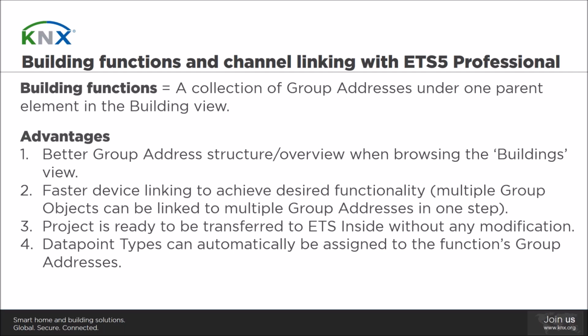Simply imagine today how much time you spend to create the group addresses and afterwards to link them with the corresponding group objects, assign the data point types, etc. This is all simplified and made much faster with the channel linking to building functions.